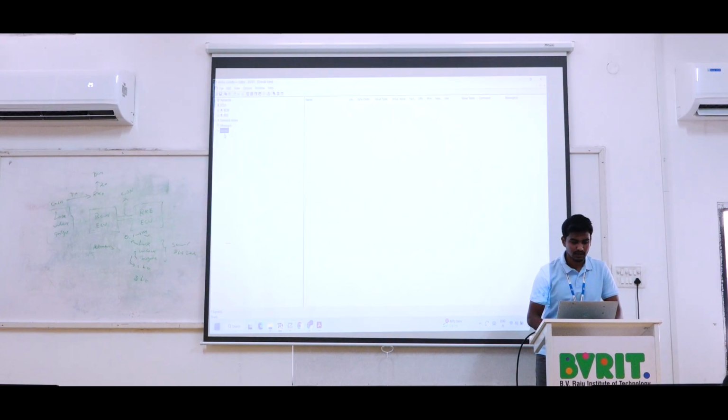Okay, going to signals here. Note down that for nodes, name, address, command will be there, and whenever you press signals, you will get name, length, byte order, value, these kinds of things. Here I can right click and open new. Here it will ask the definition of the signal. I can say the first one is lock.